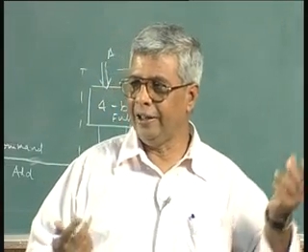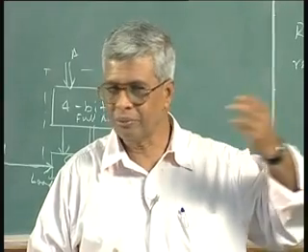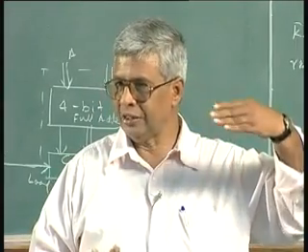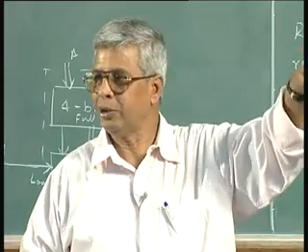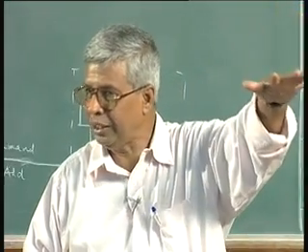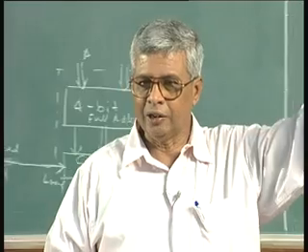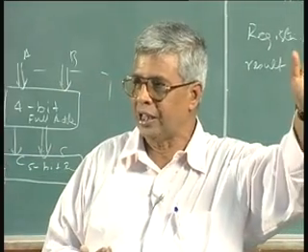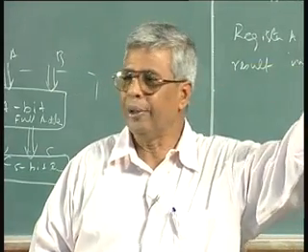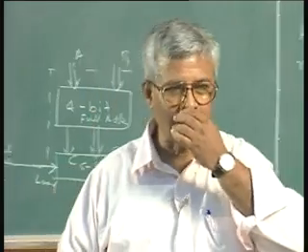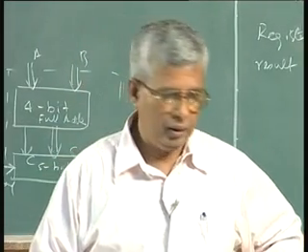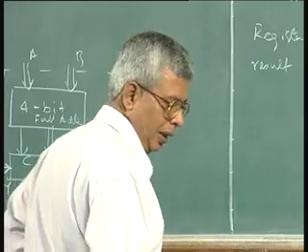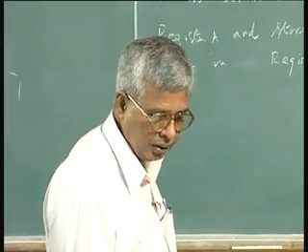Then I will have to do a state graph of the sequence of events, how to load the thing, how am I going to count it, and when the result comes, how am I going to write it into register B. All that has to be put in the control unit state graph. Once the control unit state graph is there, I will have to implement it using a multiplexer based solution, whatever is the most favorite solution of yours, right. So, first part is, as I said, the functional units.